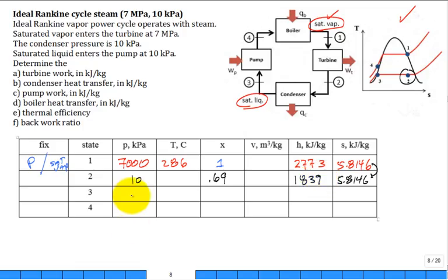Okay. What is the pressure at state 3? And then what is the other piece of information for state 3? It's pressure in a saturated liquid. Quality is 0. This H is 192-ish. And entropy is 0.6492. So you could see the enthalpy, a dramatic reduction, as well as the entropy. Can you see that the entropy really did drop a lot on the diagram?